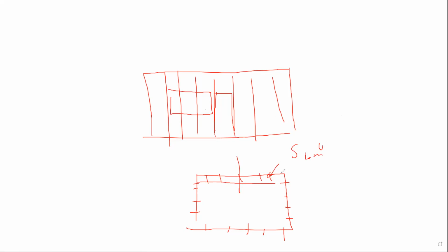Once you decide that your stud wall is going to be made out of a 2x6, then you're going to have to start designing the lintels that have to support all your roof trusses to make the openings for your windows. And therefore you'll be able to design the lintel.